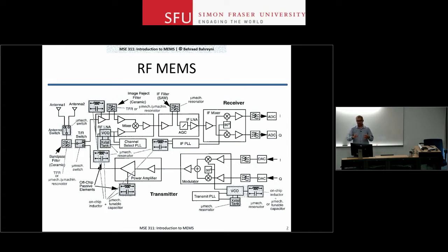And the reason for that is that your transmitter is an antenna here that is covering, let's say, an area that has a diameter of a few kilometers. And all the power that comes out of this antenna is distributed on such a large area or volume, depending on how you do it. And even if you're transmitting kilowatts of power in some situations, the receiving end is receiving only milliwatts or microwatts of power, and has to extract all the information that is sent out.